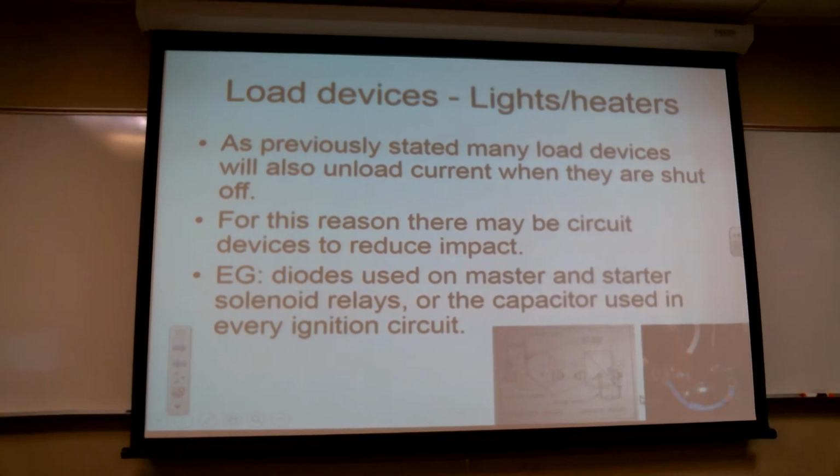typically most circuits, the high current users are going to be motors and lights. Those are both going to have pretty high rates of current coming in. The other thing that's going to happen is once they're under a load, you go to turn them off, that current's not going to want to stop because the circuit is primarily an inductive circuit.